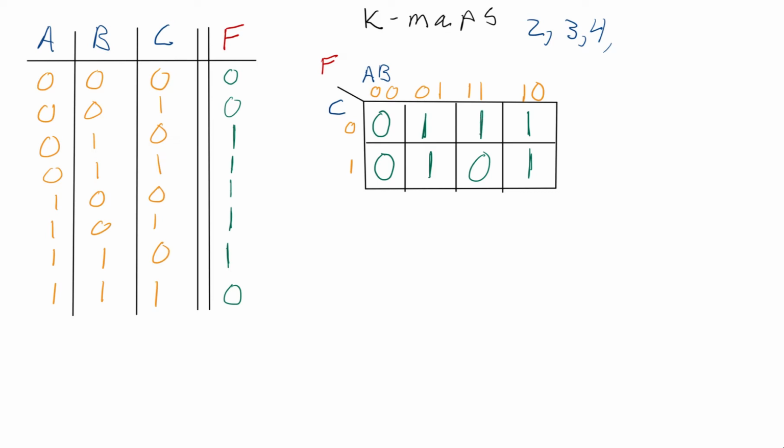Okay, so we've now filled in all of these numbers. So the way that it works, now there's going to be rules, and I'm going to give you the rules in a little bit. But basically what we want to do is circle all of the ones and none of the zeros. When we make circles, we're saying those are our high values, or the voltages that should be turned on in these conditions. But there's a couple rules with the circles.